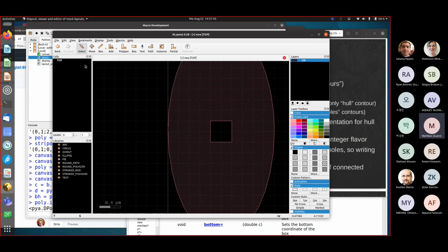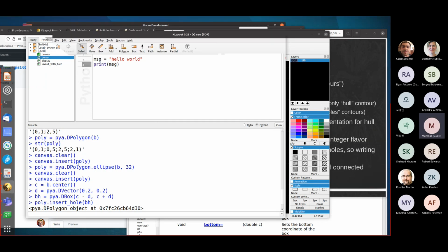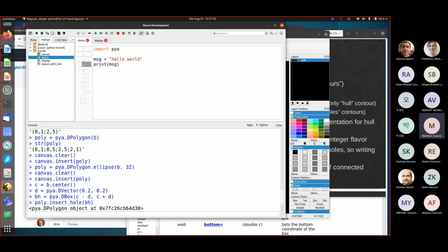it's 400 by 400. I hope this gives you a first impression of how you can work with these objects, right? So again, here I have used a point, used center, used a vector to define the displacement, and this is eventually how you are going to work if you're coding layout. You have a dimension you need to produce. By using the center, I have an exact reference to the original object. I don't need to code a specific coordinate, but I use coordinates measured from other objects. I work with points and vectors to generate new objects, manipulate objects. In this case, I was inserting a hole and so on.